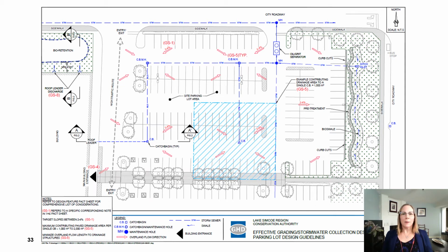You can look at curb cuts along your LID or bioretention features to allow meltwater to drain into your landscaping features. And again, noting the roof leaders, you want to make sure they're draining away from buildings and sidewalks and into catch basins or into landscaping features. In a nutshell, proper geotechnical design and quality control during construction are extremely important to ensure that settling doesn't occur, because you don't want to see that pooling in the parking lot once everything's said and done.